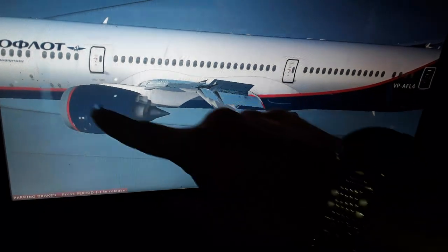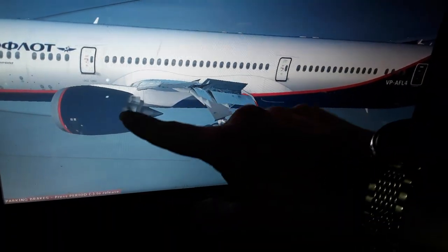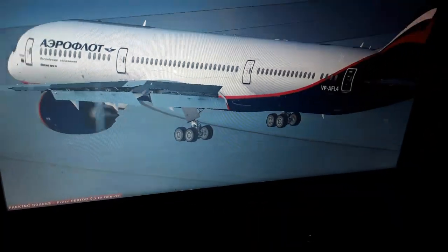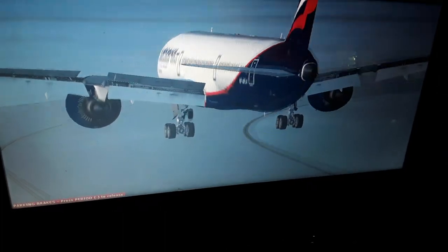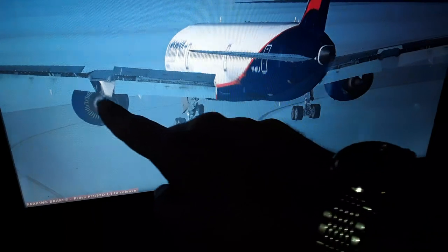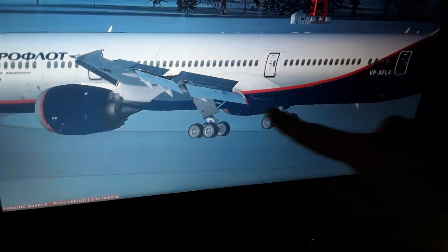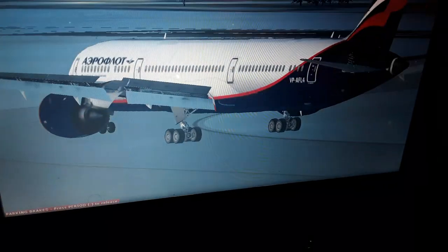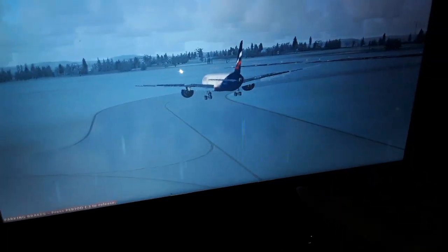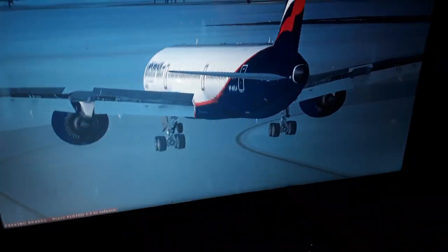We have the high pressure compressor and turbine in the back, and the high speed starter and stuff, and the low pressure compressor and turbine in the front, and the front fan. Also the thrust reversers over here. So you can see we have two flows over here. One is high speed from the inner core, from the exhaust of the engines over here, and the other one is lower airspeed, the bypass from the front fans, as you can see, of the jet aircraft, both engines.